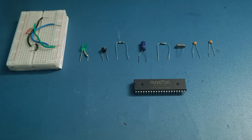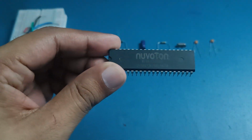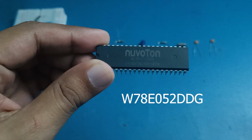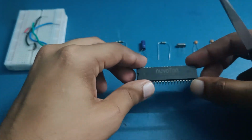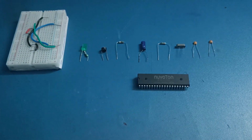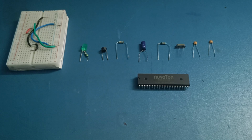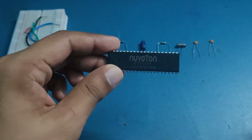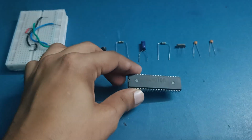In this video tutorial, I'm going to show you how to program this microcontroller by Nuvoton. Its part number is W78E052DDG. This microcontroller has many interesting features. It's similar to other 8051 based boards like 89C51, 89S51 or P89V51RD2. These are all microcontrollers which you can directly replace with the Nuvoton microcontroller. The pin diagram is the same in all of these microcontrollers.